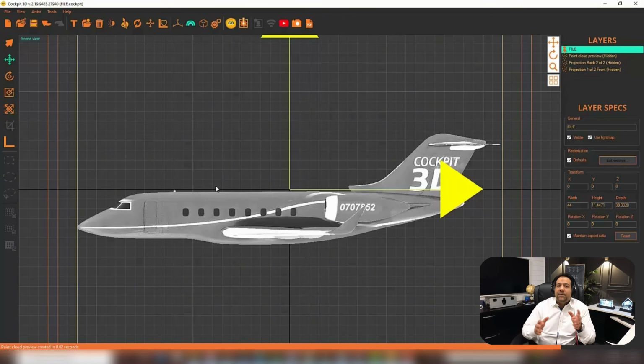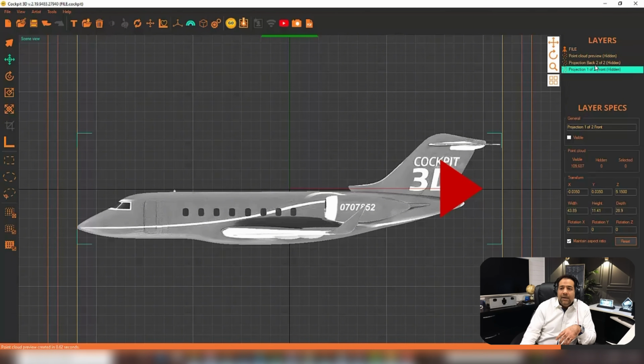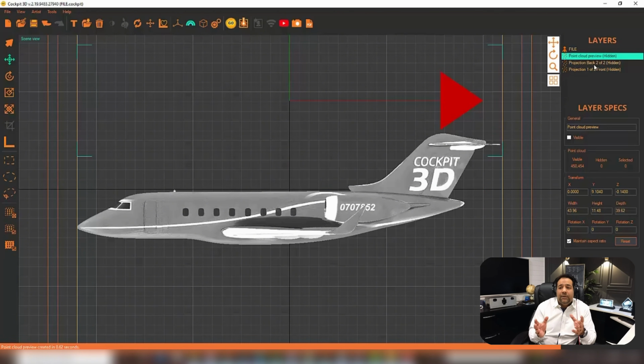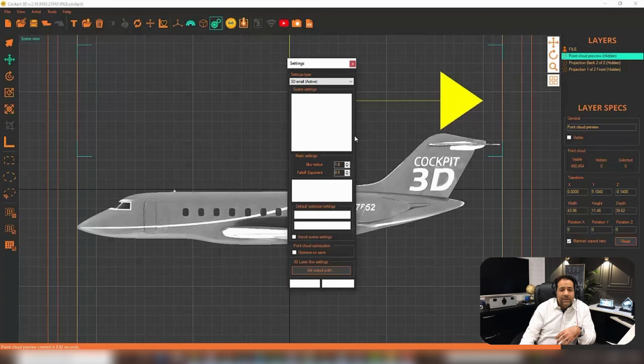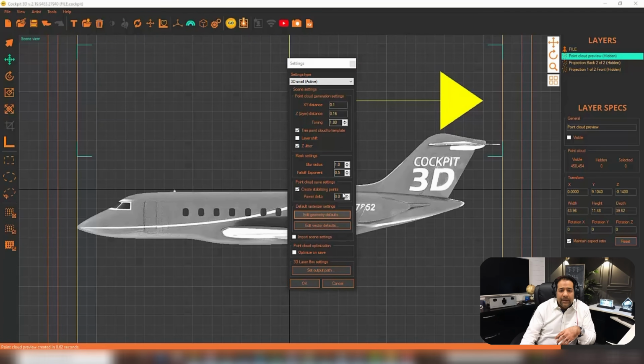The reason I'm doing that is because remember, when I burn this file, now I've got points that are coming from here, I've got points that are coming from this layer, and I have points that are coming on top of all of those from the X-ray. So let's just do that right now. Edit geometry, X-ray, okay, click on go.